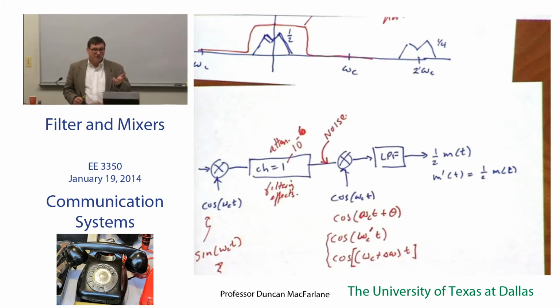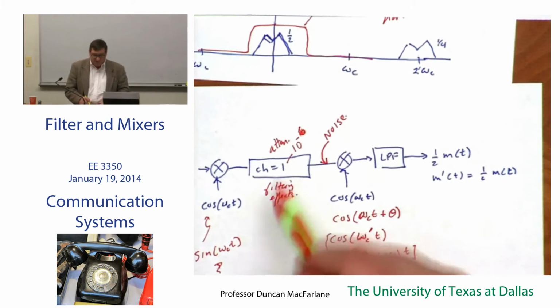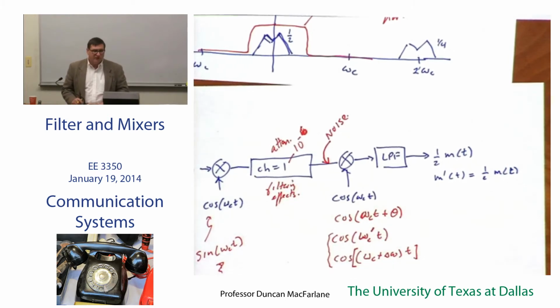Right? So if you think about your filter response, we always teach you about phase response. I find phase to be rather difficult to wrap my brain around because the phase, the number of radians, is pegged to a particular frequency. And so if I'm treating a large number of frequencies, I'd rather know this frequency component was delayed 7 nanoseconds, this was delayed 3 nanoseconds, this was delayed 6 nanoseconds. That to me makes more sense than the relative phases of all of those. But your mileage may vary. Okay? So that'll roll up into filtering effects.